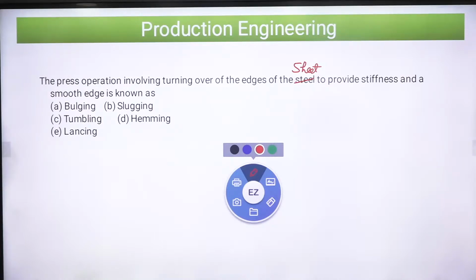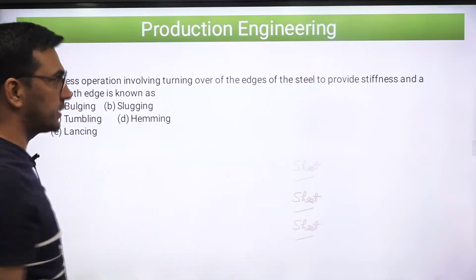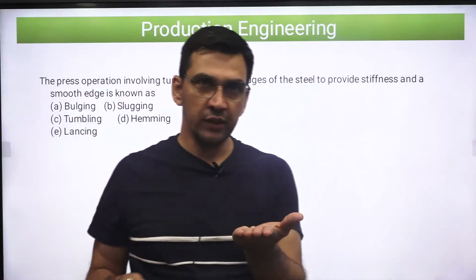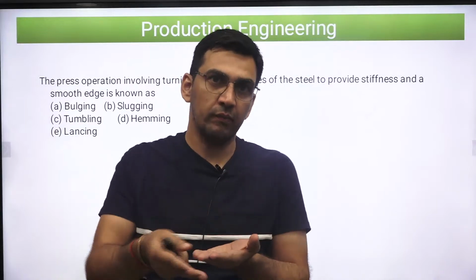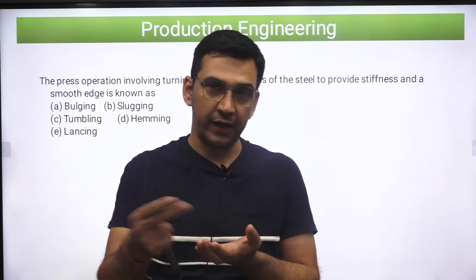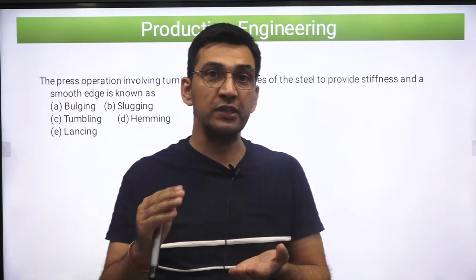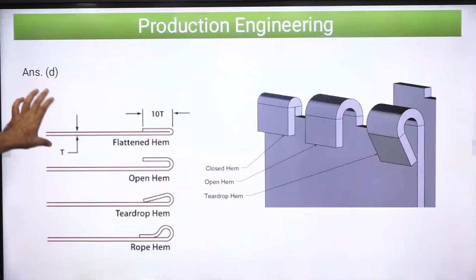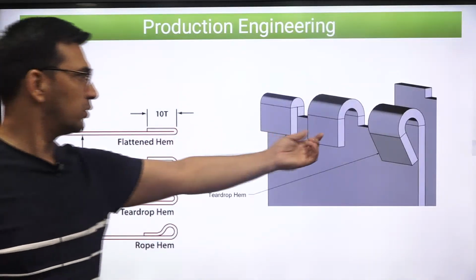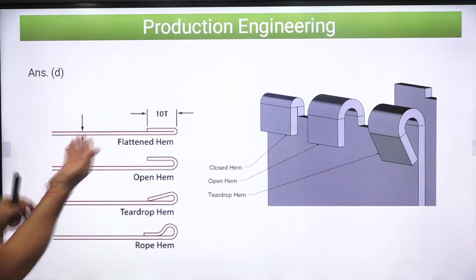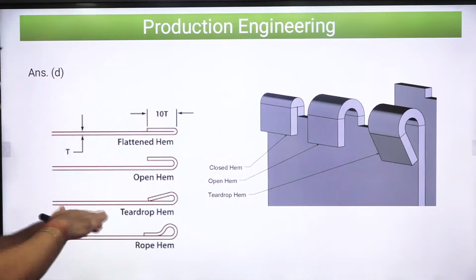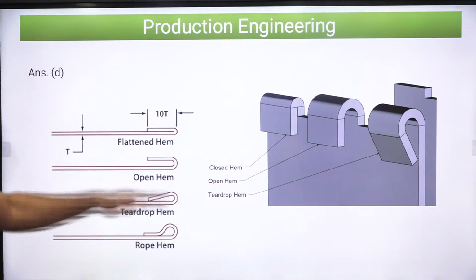Okay, good. So basically in this process, we have a straight sheet. Sometimes we fold the end of that particular sheet so that the end becomes blunt and doesn't remain sharp, right? That we call a hemming process. This is highly enlarged, so it looks like a very high thickness, but you take a sheet, fold it from the end, and then press it. That process we call hemming.